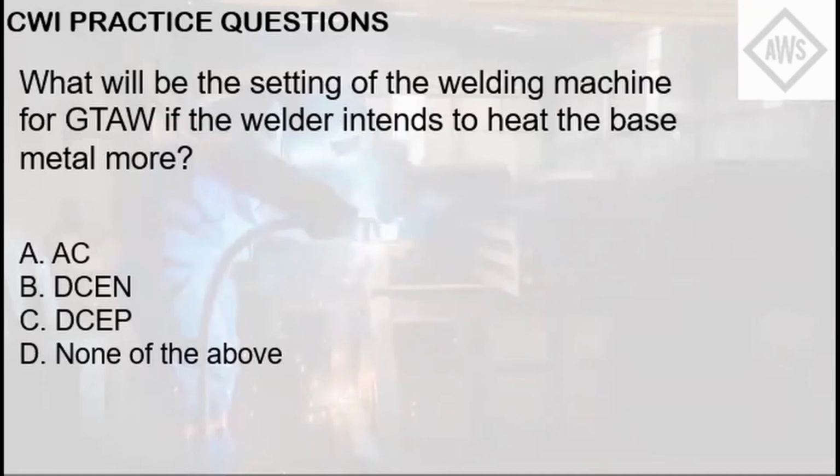If you plot the current, basically the electrode is not in contact, or it seems like it's not in contact with the metal for a very long period, much more like SMAW. You can use AC because when you run out of the electrode, you basically take out the contact of that filler metal to the base metal. So it is okay to use AC for that.